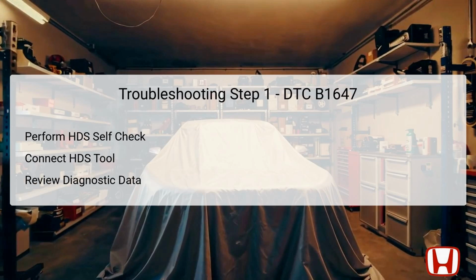The first step in troubleshooting DTC B1647 involves performing a self-check using the HDS, or Honda Diagnostic System, tool. This involves connecting your diagnostic tool to the vehicle's OBD2 port. The HDS will initiate a communication check with various control modules, including the body control module and the keyless access control unit.